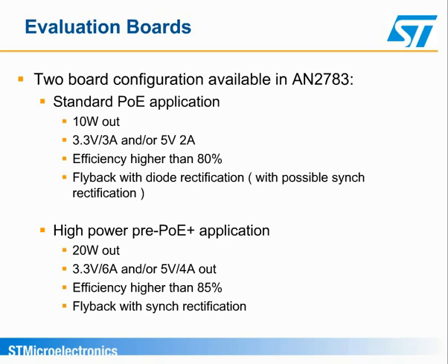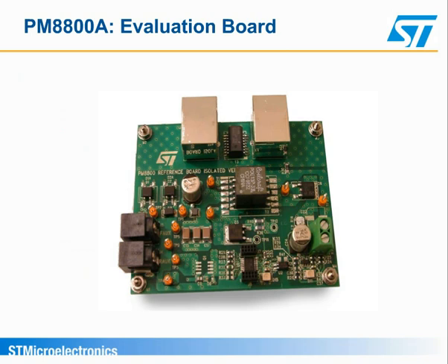This board configuration can show capabilities of both high-power applications and of working with wide input voltage auxiliary sources. This is allowed by the transformer selection. Two different output voltages are possible in both power cases, 5 volts and 3.3 volts. The board intended for IEEE 802.3AF applications is shown.